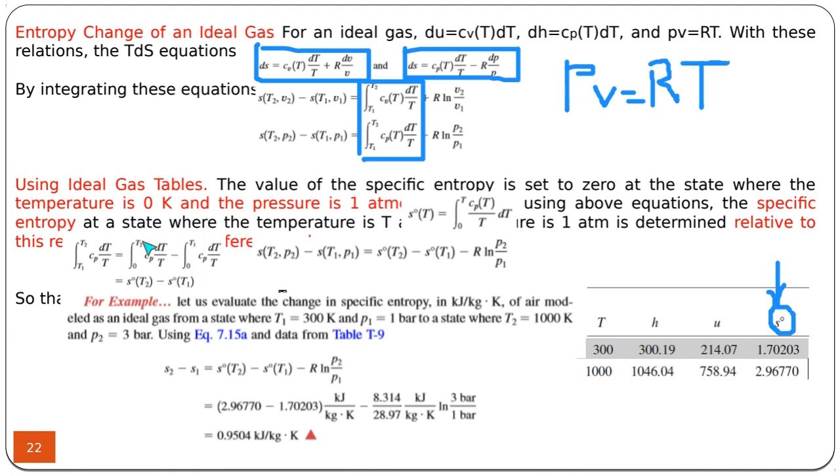So the change in the entropy, this integral minus that, is obtained from the tables by using the S0 values. So we do not need to deal with the integrals anymore. We can use the S0 values given in the tables. Then the first equation or the second equation becomes this one. These are the values obtained from the table. They are the values of the integrals.